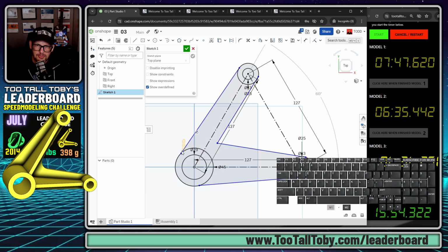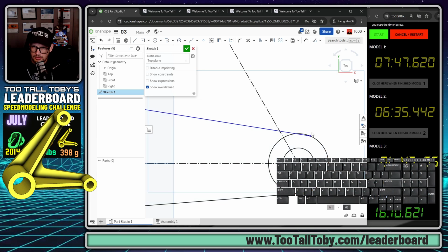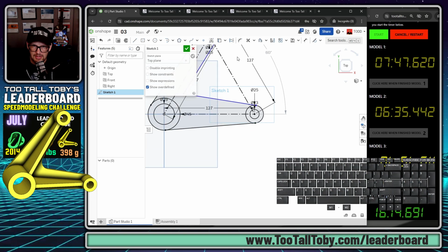And then for some of these, you could do a crossing. So do a little crossing here, press T for tangent. This one looks like it's already got tangent, so that's pretty sweet. Over here, we could do a little crossing, T for tangent. This one here, little crossing, T for tangent. And it looked like this one moved at the same time. We don't necessarily want that to be vertical to that other point, but we do want this to be tangent. So T for tangent to get that lined up.